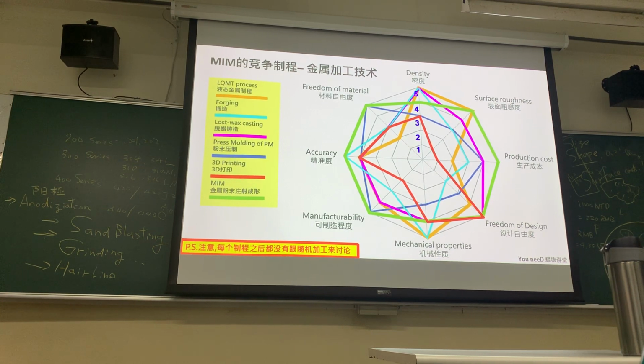For example, for MIM, we need less than 30 microns, but we also choose just 1% to 2% boron powder added, which is about 1 to 3 microns. Very small, but the quantity is super huge. We mix it again, separate, then we can cut it well.